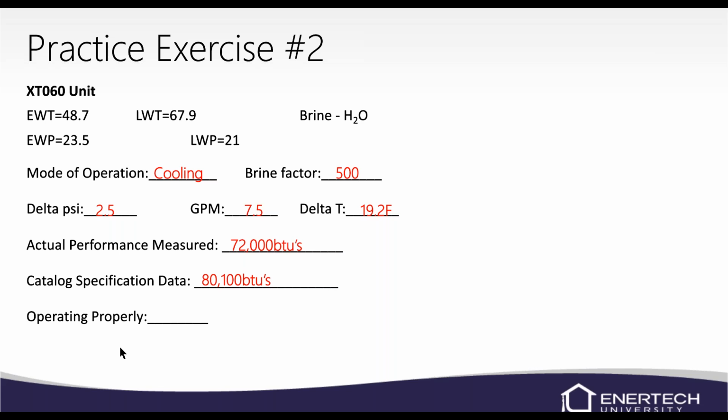the air coil. If it's keeping up and you're only there for maintenance, I would probably make a note on the ticket of what the BTUs were and make sure that you check it again the following year to make sure that number hasn't gotten even farther outside of its range. But it is operating within 10%, so there really is no need to put refrigerant gauges on there unless for some reason they called because it's not keeping up. And then they probably just sized the unit too tight and it's really cold outside or something like that. But again, yes, it is within the 10% in this example, just barely, but it is within specs.